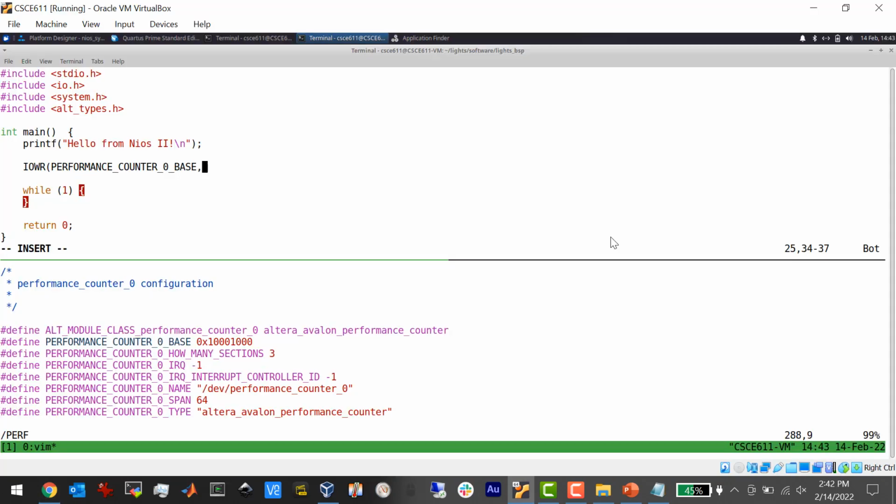and that would be outside the loop. So now another thing that's strange here is that one should really be a 4, right? Because the control registers, which is what I'm writing, are 32 bits. So if this is the base and my offset is there, then that shouldn't be a 1, that should be a 4, right? Well, it's multiplying that by a 4 for you, right?